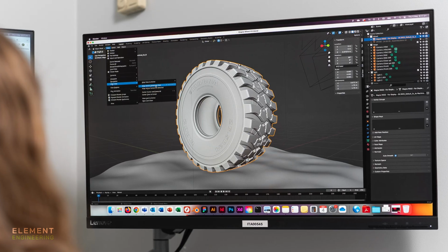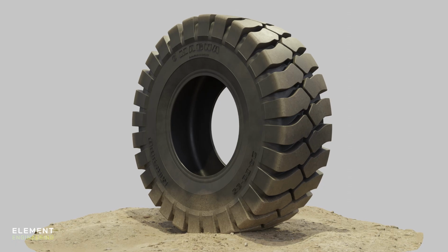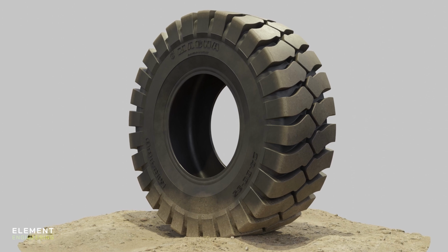There are other generic things I would say, like making sure that you're minimizing your feature count where possible. Back in the day, when computers weren't as powerful, you didn't want to use 300 features to create something that's relatively simple. You want to try and group things and be smart about it. A good example would probably be, even the old tyre models that we used to do, the side wall text was modelled. We used to use thin lines, remember? Oh, yes. Yeah. It looked great for the renders, but it was horrific for the feature tree.